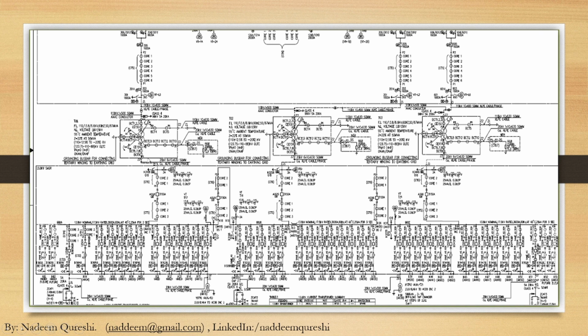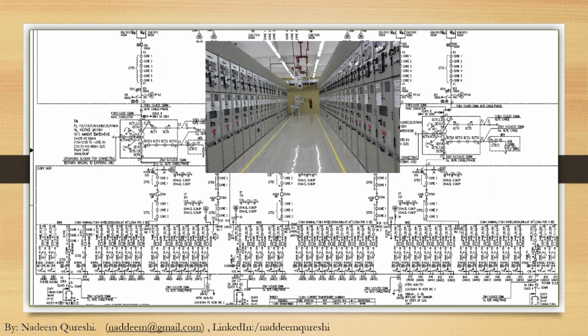The secondary of this transformer is again feeding another switchgear voltage level, which is medium voltage 13.8 kV. So the transformer feeder from GIS is an input to the transformer, and this incomer feeder to the 13.8 kV bus is an incomer feeder for the 13.8 kV bus.